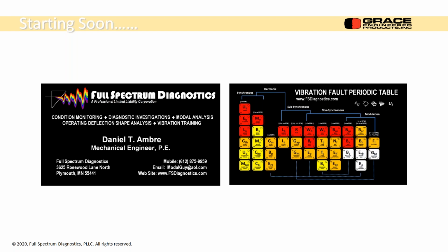CTC Technology. Anyway, they're small shaker units, and you can attach your accelerometer to it, and you put a 1G 100 hertz signal into it, and it'll tell you how far off you are from that. So it basically starts at 100 millivolts, and the drift in that will tell you where you are. You might be, it used to be 98.4, now it's 96.2. It doesn't change the calibration, it just tells you where you are now. There's always a little drift in the calibration factors over time, but not much.